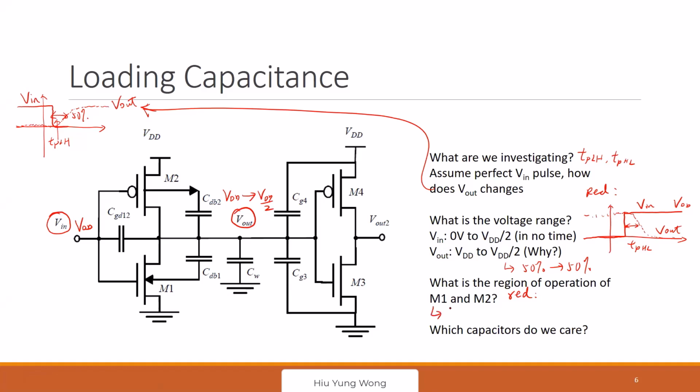So what I'm asking is, right at the beginning of switching, this one goes from 0 to VDD. Maybe I should write it better. From 0 to VDD, right? Before, when it was at 0, this one is at VDD, then it suddenly becomes VDD. Then it will start gradually changing to 0, and you pass through VDD divided by 2. But right at the start, this one is still at VDD, correct?